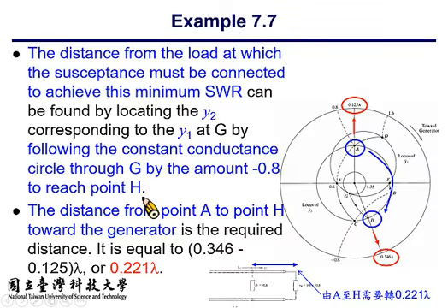All right. Before we conclude the problem, as on the Smith chart, we already demonstrate that the optimal shunt position is H. So you need to calculate, or you need to find out how much distance that you should travel to get to point H. So remember that you're starting from position A, which is on top of the Smith chart, and you need to move to position H, which is down below. And what is the distance between A and H?